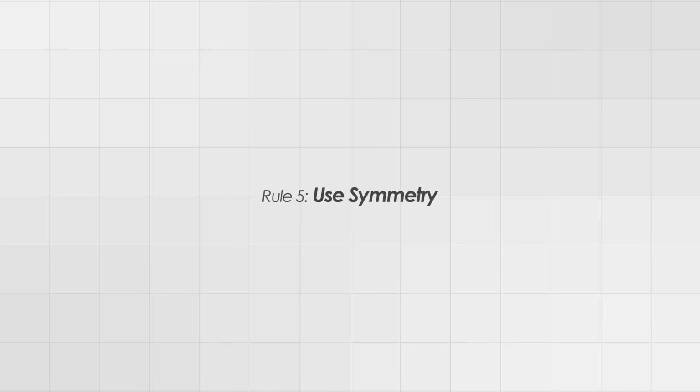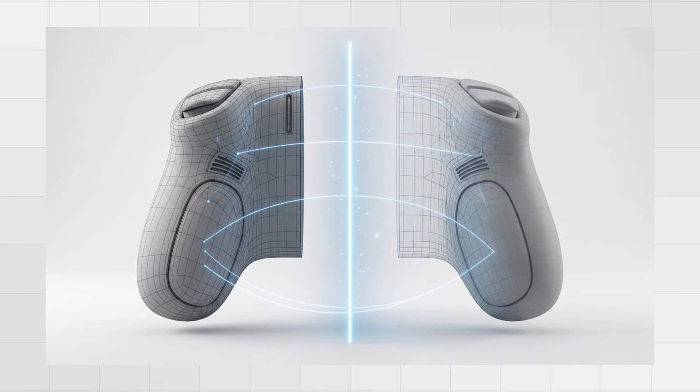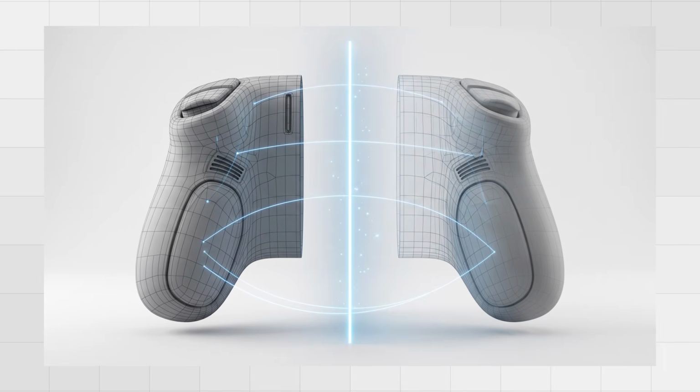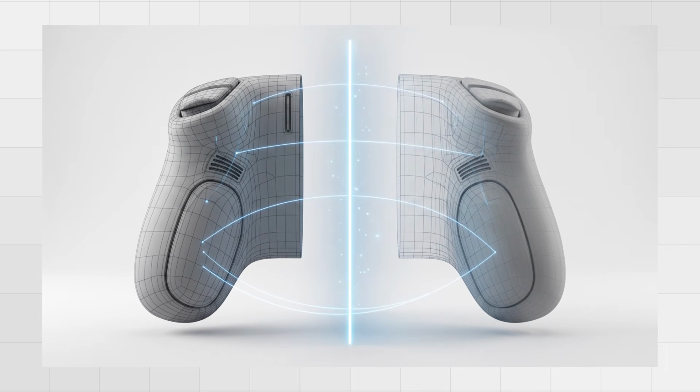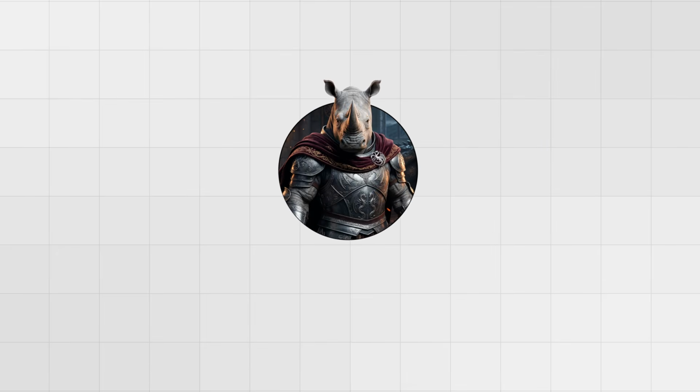Rule 5, use symmetry. If your model is symmetrical, there is no need to build both sides separately. Using tools like Reflect, you can design one side and generate the other side automatically. This not only increases your speed, but also reduces mistakes. In the end, a good SubD model is not the one with the highest number of edges. It is the one that has exactly the right amount of control for the shape you want to create.